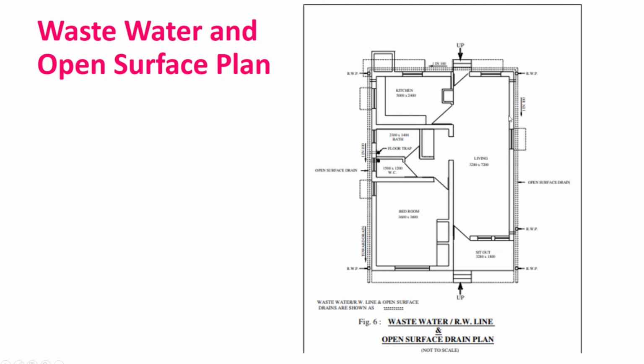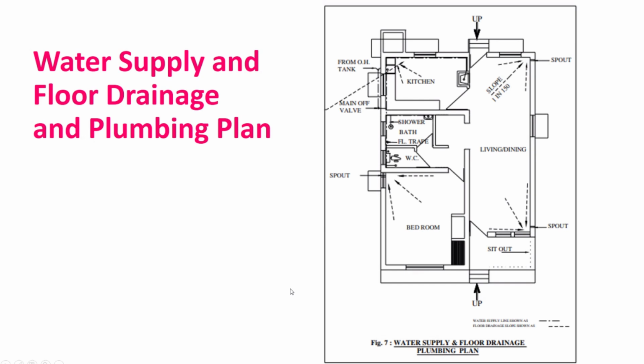An overhead line shall not cross an existing building as far as possible, and no building shall be constructed under an existing overhead line. And they have given certain things. Now here you can see these may be private, again small plots which are just coming up in and around this particular electric tower. Now you can see the design itself, they are making use of this and possibly they are using it just like a road.